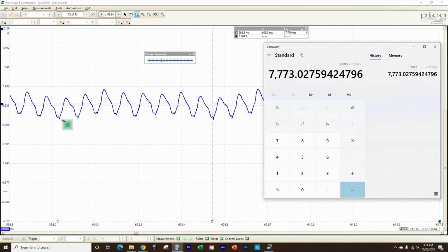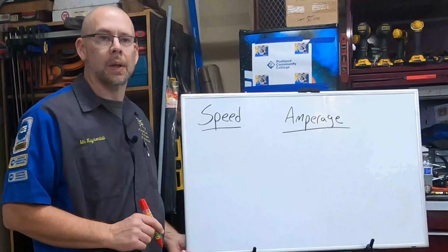So we're going to look for something common in the waveform, a repeating pattern on which we can line up our cursors. And when we find that and set up our cursors, then we count the number, because we should have typically 8, 10, or 12 of these bars or humps in here. And then we're going to see how much time was between them, my delta box up here in my cursors, and we're going to divide 60,000 by that number to give us our RPM.